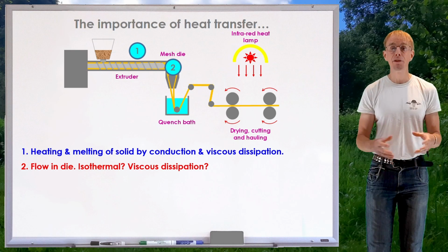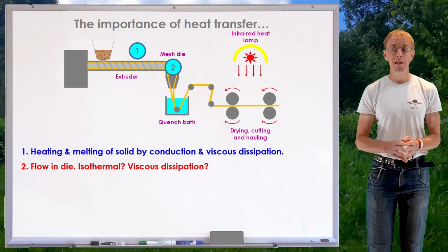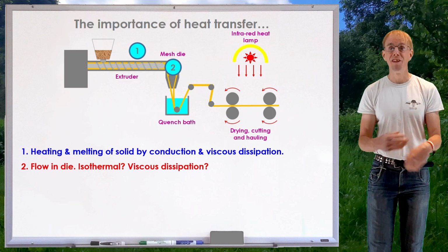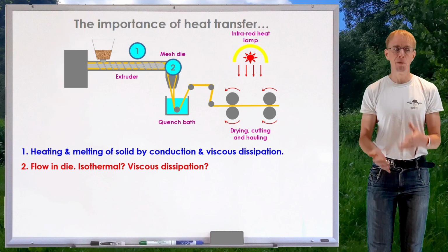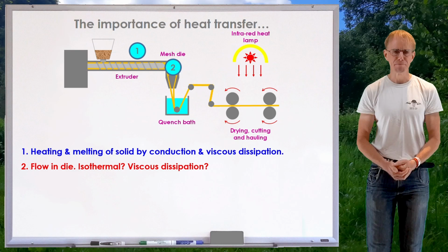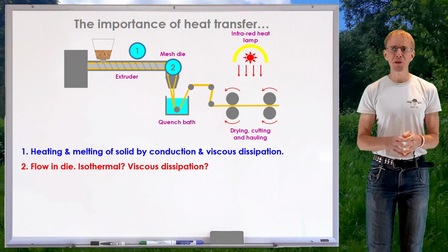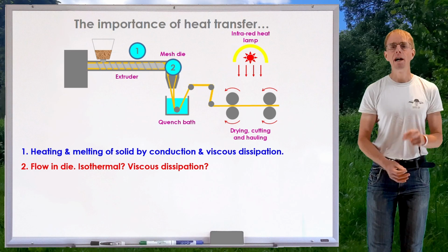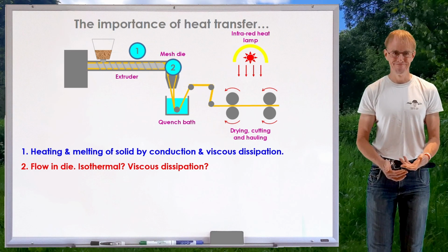That can have a significant heating effect on the liquid phase in those high shear rates, which in turn alters their rheology, because we now know that the rheology of polymers is very temperature dependent. And so even though we might design our die to be isothermal, it may well not be as a result of the flow within it.